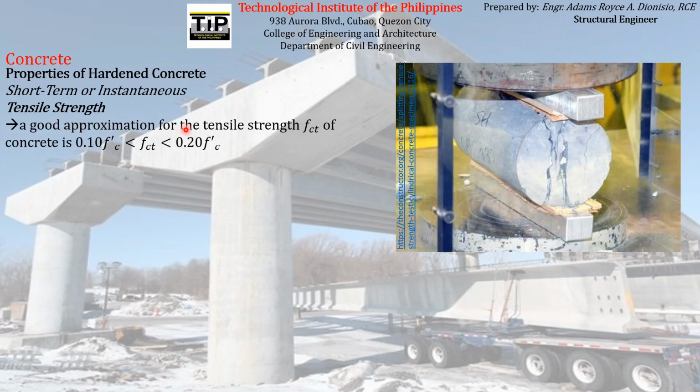A good approximation for the tensile strength f_ct of concrete is 0.1 f'c up to 0.2 f'c, or 10% to 20% of the compressive strength of concrete. So usually the tensile strength of concrete is just between that range, 10% to 20% of the f'c. You can notice that the tensile strength has a significantly low value compared to the compressive strength of the concrete.